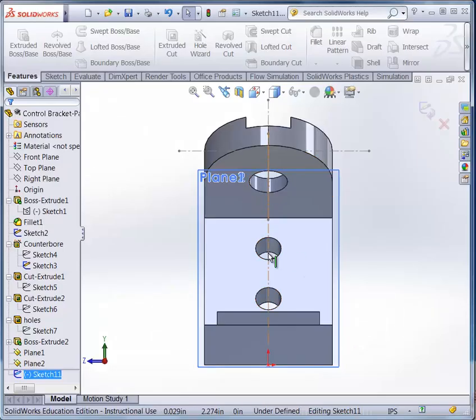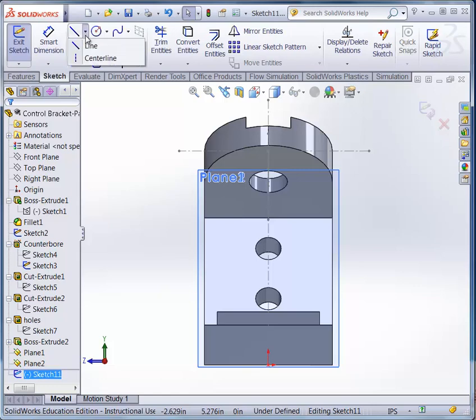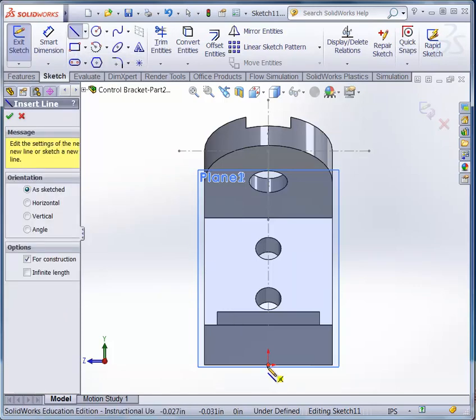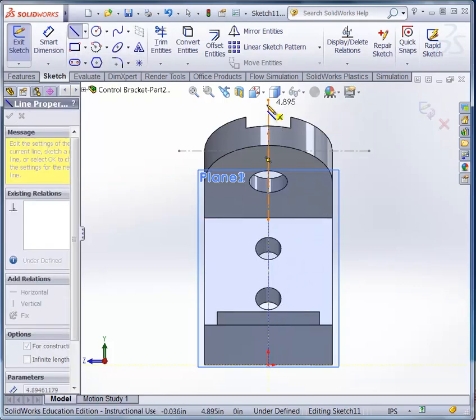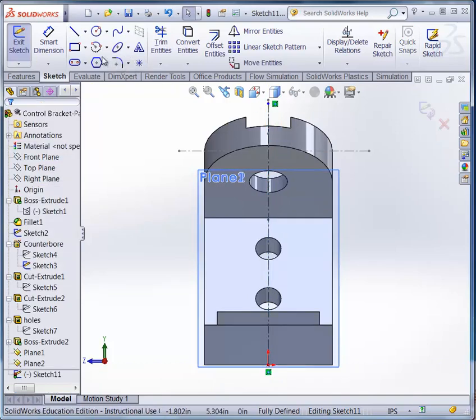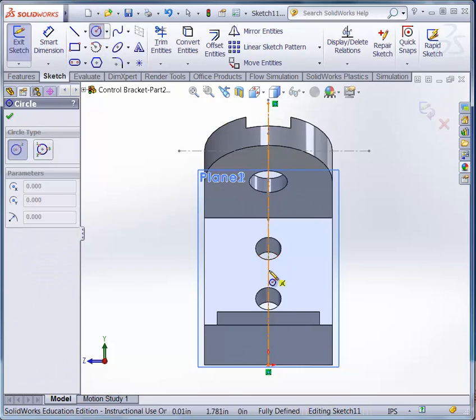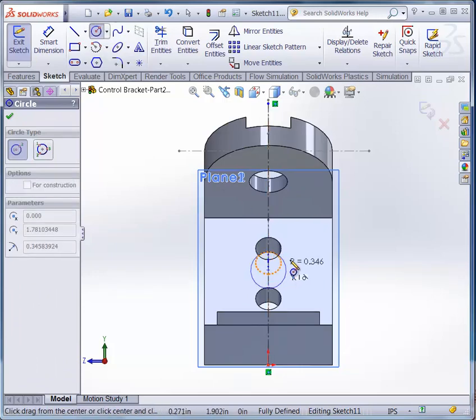All right, so here we are. Again, you can see the origin. We can establish a center line if we like. Why not? Let's go to sketch and use center line. Projecting from the origin, creating a vertical construction line, and escape. Now, somewhere along that line, we should make coincident the center of our diameter.